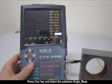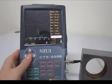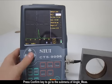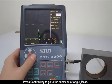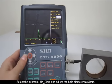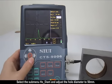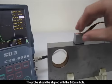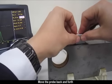Press Correction key and select the submenu Angle Measure. Press Confirm key to go to the submenu of Angle Measure. Select the submenu Hole Depth and adjust the hole depth to 30 mm. Select the submenu Hole Diameter and adjust the hole diameter to 50 mm. The probe should be aligned with the Φ50 mm hole.